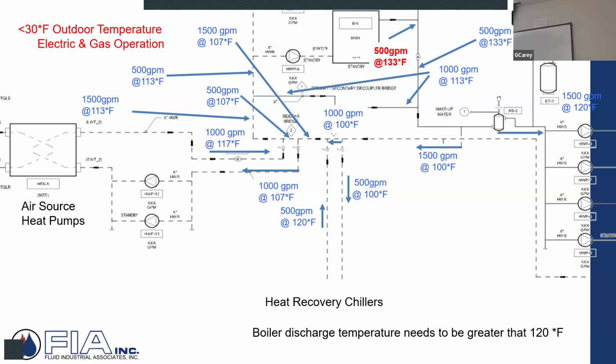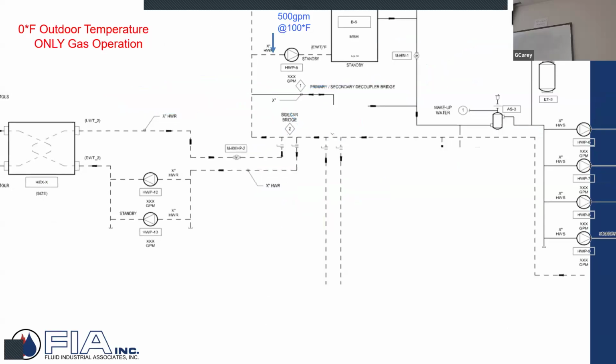And so I can have all of this different pumping. These pumps don't even know the other exists, and they're all working together without fighting each other. All because of the decoupling, the low pressure drop, whatever term you want to use, so they're not in series and fighting each other. And then the final scenario would be, hey, it is cold. It's New England. It's Boston. It got real cold. Maybe the COPs and the air source, there's nothing there.